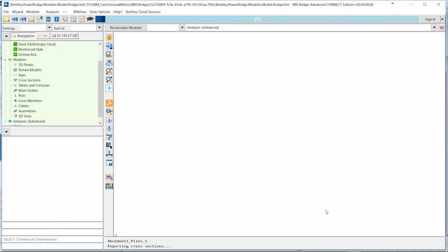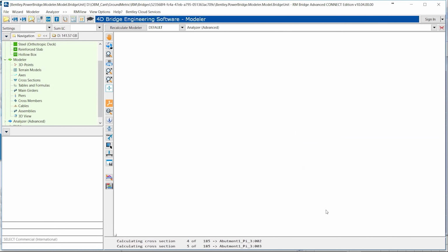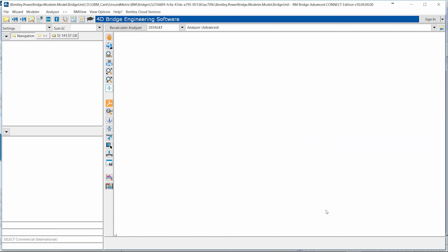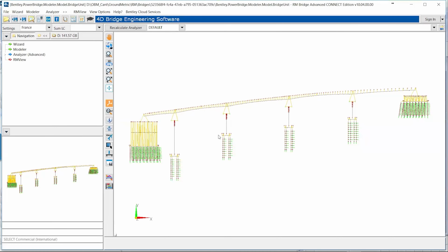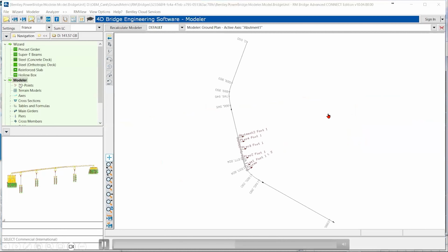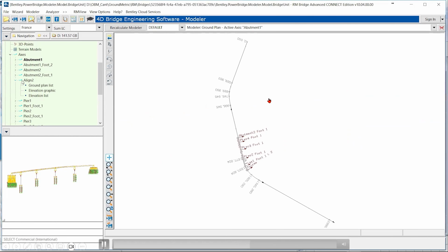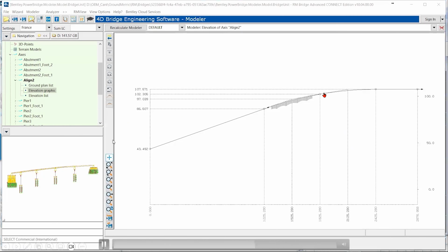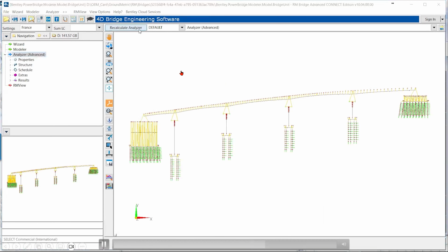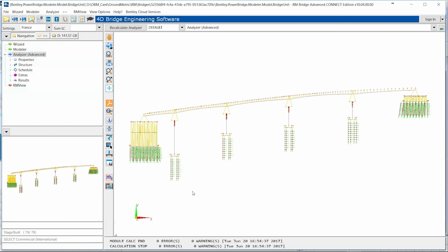So we enter exactly the same file, but the geometry in that case is updated. If we have changed the cross-section, it should have been changed during this process, or if we change different types of the support, the same way. But all the rest, here we can see that we have a different geometry, for instance, that has been updated, okay? But all the rest is not modified. That means that after sending, we can directly send the calculation without redefining the load case, because everything was stored in our model. It's just a model that we update.